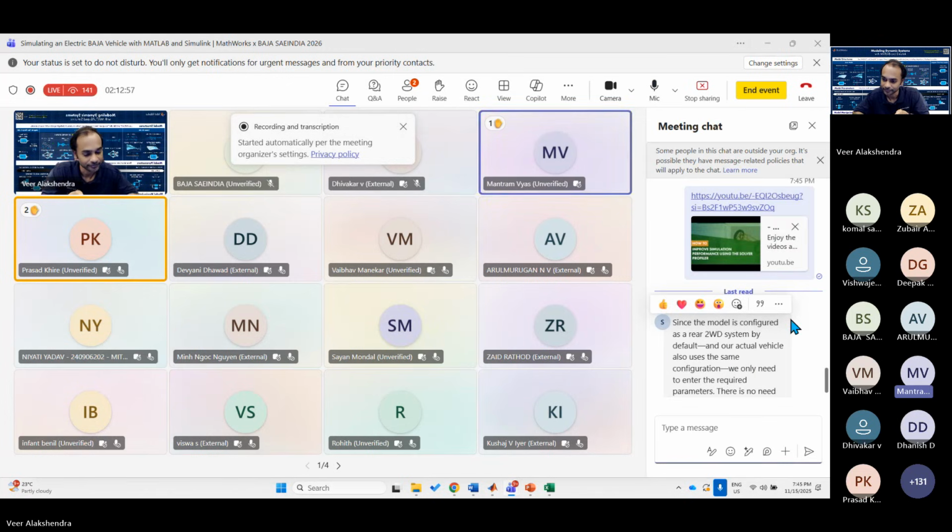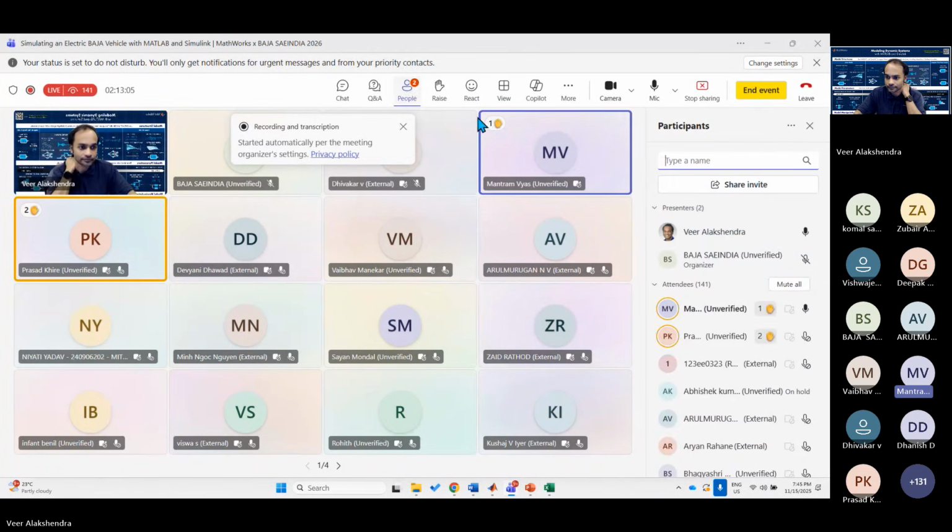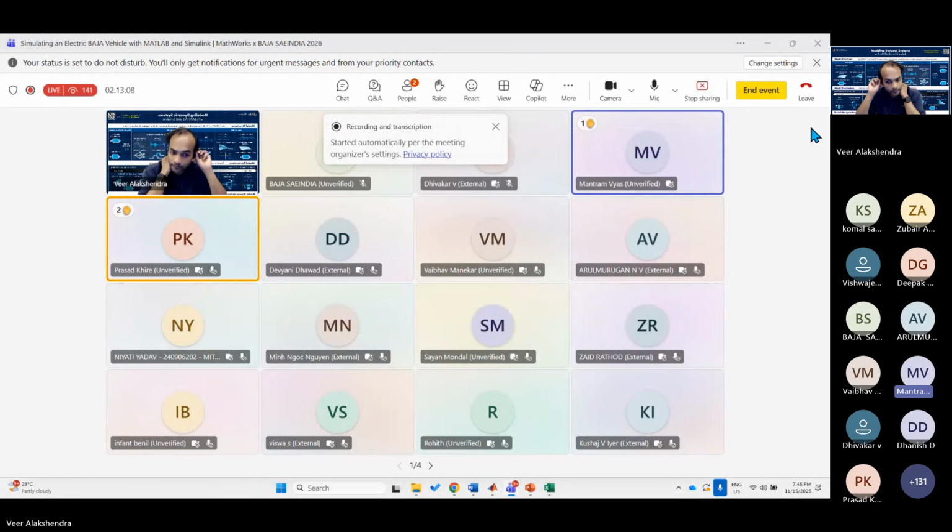Another problem is that initially, when I use some default parameters and add the parameters for the battery, motor, and drive shafts, we are getting an error that the range is almost zero, or about 300 meters, and the velocity also drops to zero. But the drive cycle is as it is, as the input. Is the problem in the battery or in the motor controller?